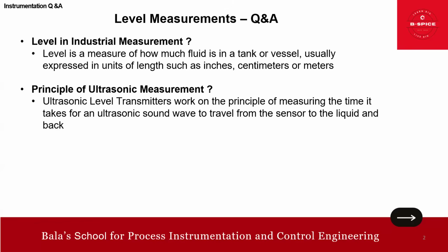Then, what is the principle of ultrasonic measurement? Ultrasonic level transmitters work on the principle of measuring the time it takes for the ultrasonic sound wave to travel from the sensor to the liquid and back to the sensor.